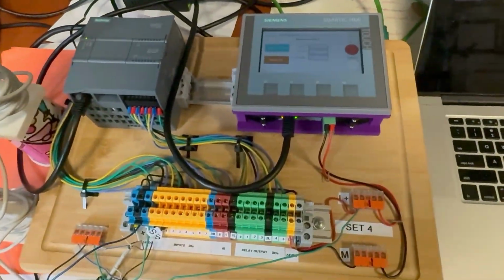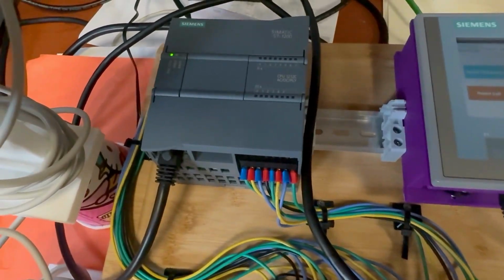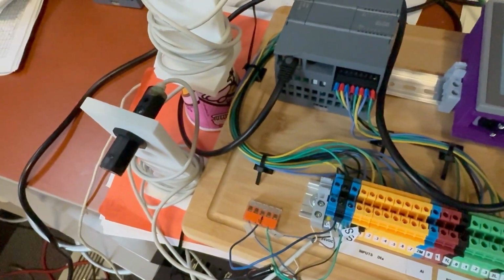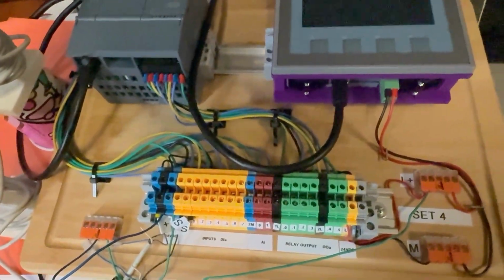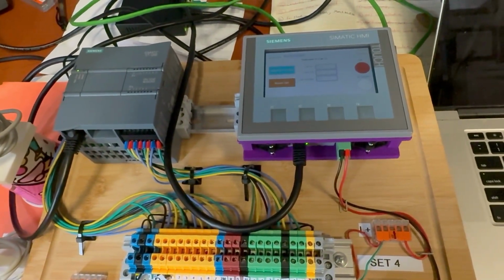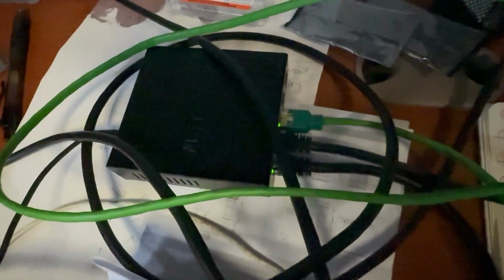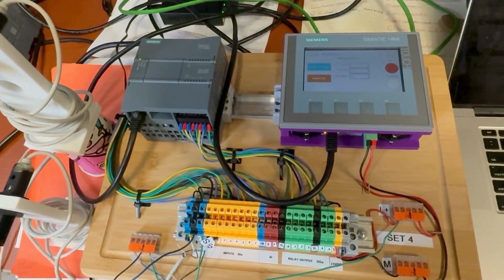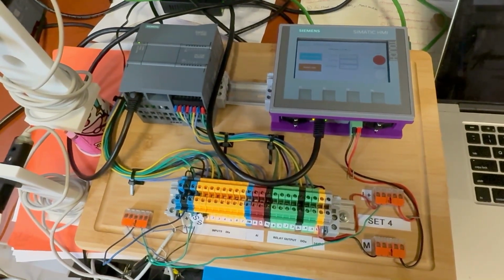Before I start to work with the software, just take a look at the hardware that we need. We have our PLC, we have our HMI. We have 2 sensors. This is for exit, this is for entrance, and these 2 are technically connected to ports 0 and 1 in our PLC. The PLC, HMI, and computer all connect to this switch that you see here through the cables. The first cable is for the PLC, the second one connects to the HMI, and the third one connects to the computer. So let's go to the software and see how we could program that.